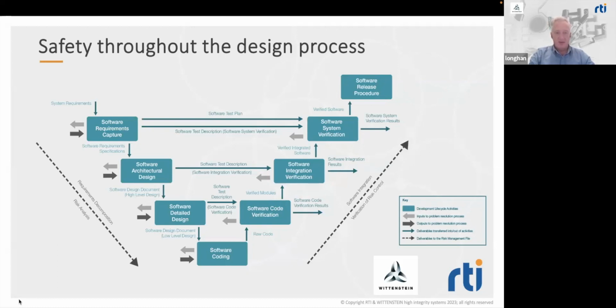We took the FreeRTOS functional model, the basic algorithm, and implemented a HAZOP to identify a set of safety requirements. We then put the functional and safety requirements through the safety critical design lifecycle shown to create SafeRTOS and its design assurance pack. By following this safety critical development lifecycle, we help to ensure SafeRTOS has a highly deterministic behavior.